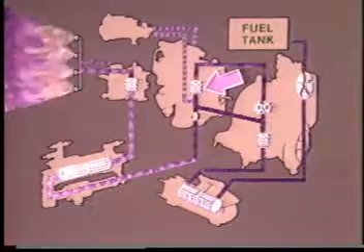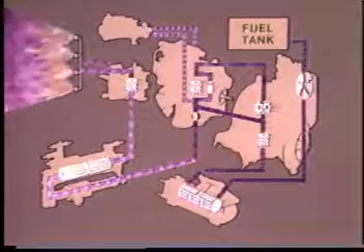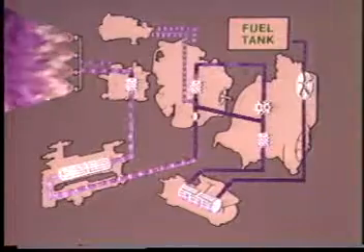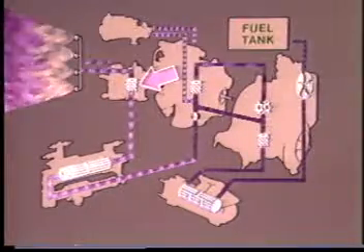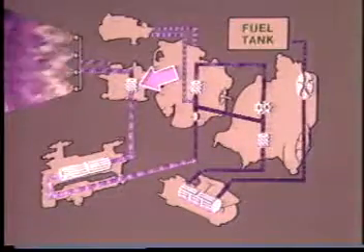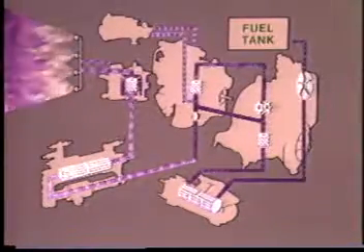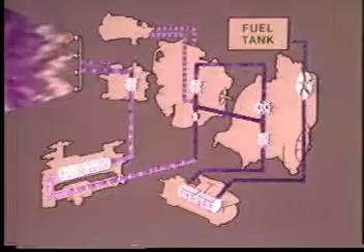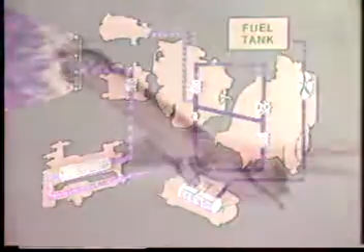The fuel control filter assembly has a bypass feature that operates at 15 pounds of differential pressure. The pressurizing and dump valve also has a filter. If it becomes contaminated, the filter will self-bypass at 10 to 12 pounds of differential pressure. This has been a brief description of the JT8D-200 series fuel system. The operation of this reliable engine is dependent on the proper operation of its fuel system.